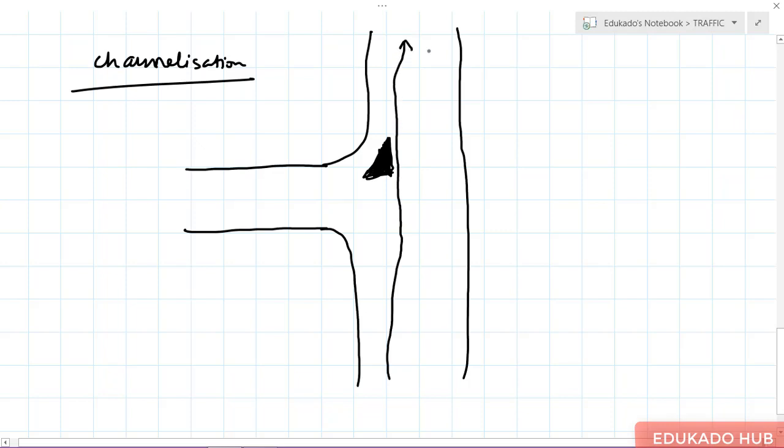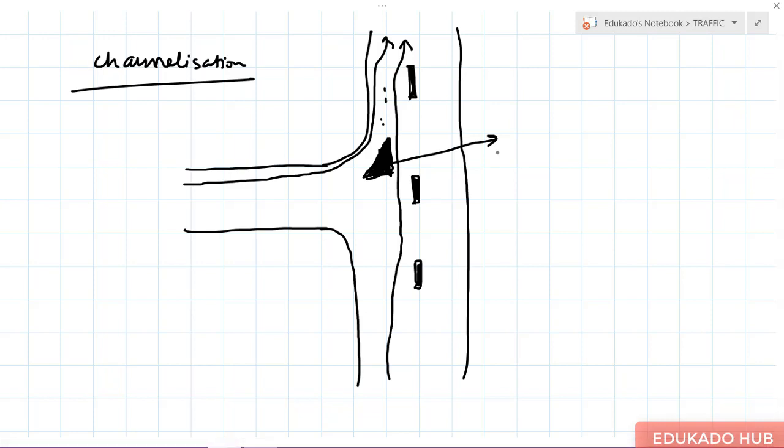On this, they will remain on the same lane. Now, if any vehicle has to come from here, it will just take a turn from here, and afterward it will join the highway. There won't be any conflict over here. So to avoid these conflicts, such things are drawn, and so that you don't cross the lanes, obviously you will provide some dividers. This process, the raised area to guide the vehicles so that the conflict area is reduced, is known as channelization. Okay.